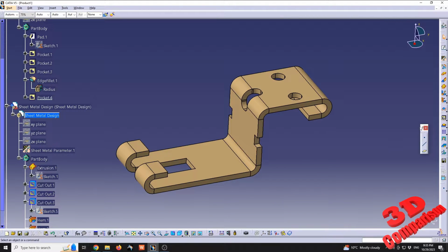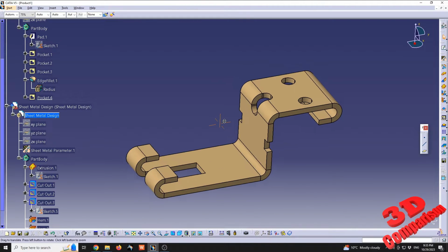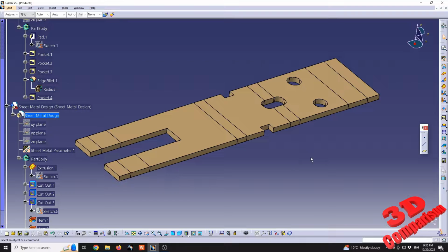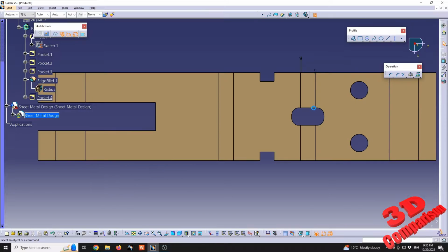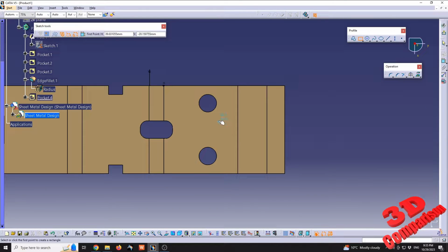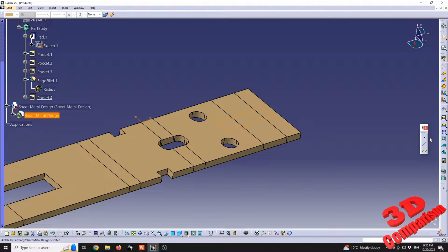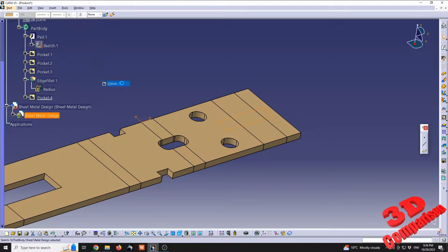Another advantage is that we have the possibility to go over here with fold and unfold, and we can do those cutouts either in the final design part like here, or we can have it unfolded, and afterwards we can go ahead and add additional cuts. So while this is unfolded, for example, I'm just gonna rapidly position something. I'm not gonna constrain it, and we can have a cutout for this. So as we can see, I don't have those toolbars added, but we're gonna have the cutouts over here, which will be that one. So the cutout, the handle is null in this case.